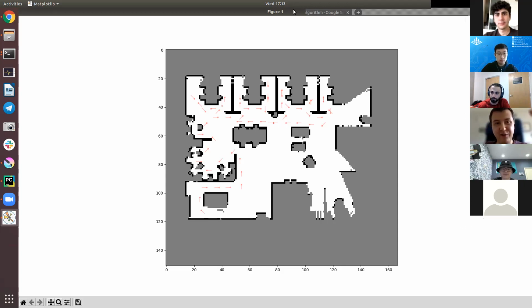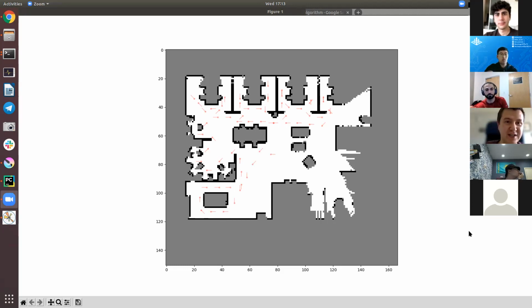Something like how often does your LiDAR tell you that a particular location is occupied when it's actually free, and how often does it tell you it's free when it's actually occupied? So this delta lambda comes from there. It's some property of the sensor. So if you can test your sensor in advance, you can fix that value, and you don't have to change it online. I believe in the demo we have some fixed constant, which I think should be log of 4. Is that the case, Arash?